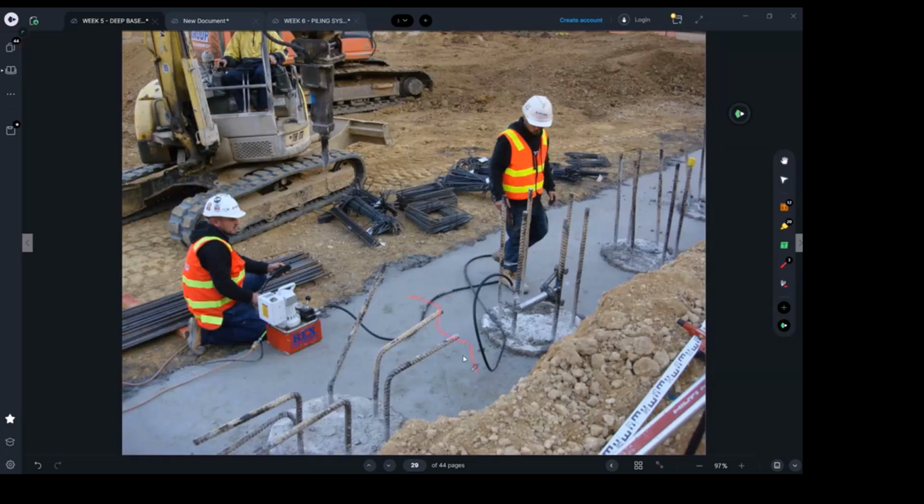What they did here, they just stabilized the soil, right? Maybe here it was very disturbed soil, so they just prepared a strong base. So don't get confused. Some students think this was the pile cap. No, the pile cap should be coming over the piles and the steel of the pile cap. See, they're preparing all the shear ligatures, the bars. It's ready to be placed in position.